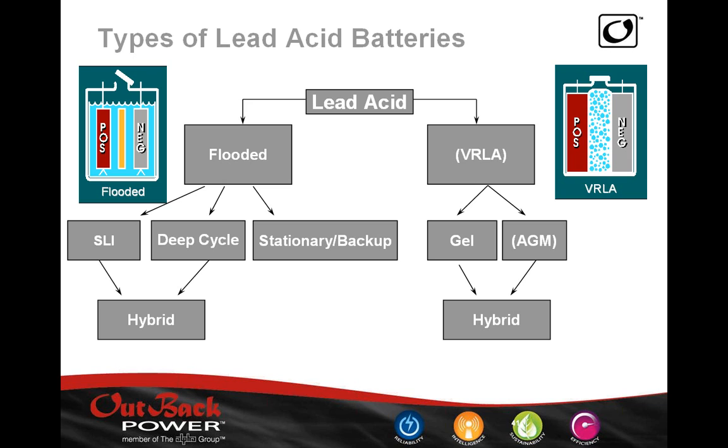A good example is systems where the batteries are going to be used one time per week, so the batteries will see 52 cycles throughout the year, but basically 6 days out of the week they're going to be on float. So they do serve as dual-purpose backup and cycling type batteries, and AGMs lend themselves very well for that.